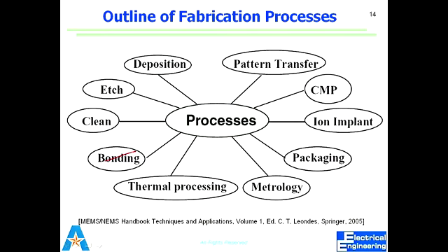We might be cleaning. Cleaning is very important because our devices are so small, they're even smaller than specks of dust. So if you have a dust particle land on your wafer and you keep on processing, we'll lose many of the devices, which is a matter of yield, right? If I don't get high yield of devices, they're going to fire me, right? So we need to keep it clean.